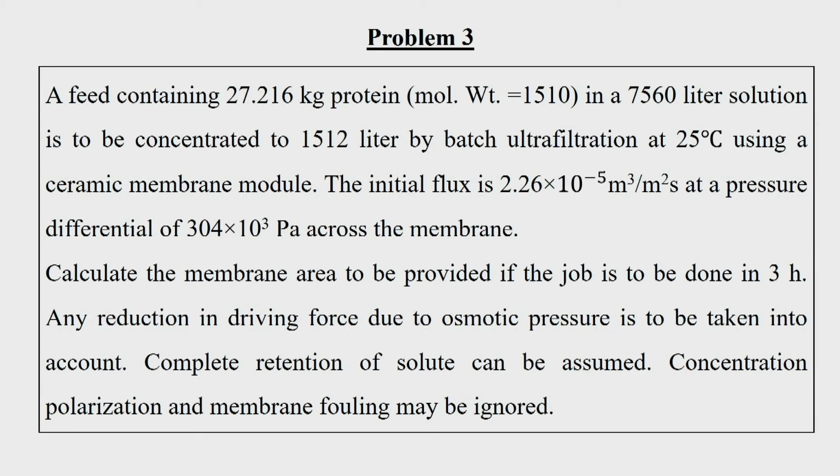The initial flux value is 2.26 into 10 to the power minus 5 meter cube per meter square second at a pressure differential of 3.04 bar, that is 304 into 10 to the power 3 Pascal.